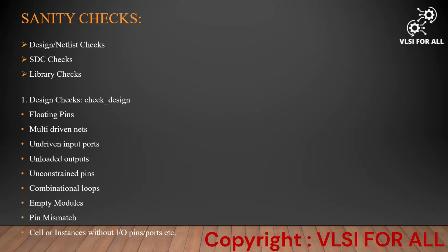Coming to the next stage, sanity checks. Once we receive all the inputs, we have to check the input files for any errors or issues. It is categorized into three types: one is design or netlist checks, another is SDC checks, and another is library checks.